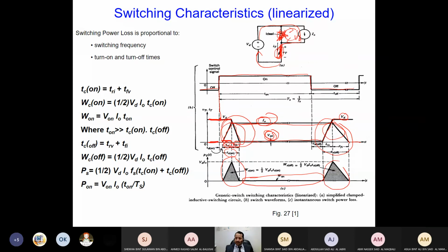The problem, again to summarize, is that when we deal with power electronic circuits, converter circuits, we use the semiconductor switch to work as a switch, on or off. That's it, done. But the problem here is that when you switch on and switch off, there is heat, energy dissipation that needs to be dissipated.